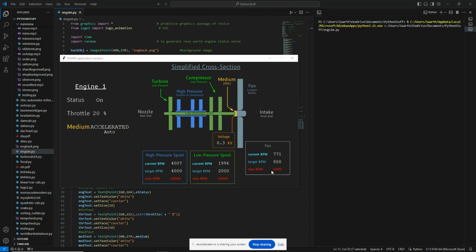So if something that's spinning at 4,000 RPM with this large of a radius is compared to something that is spinning at 10,000 RPM with a smaller radius, they would both have the same linear velocity at the tip of the fan blades. Therefore, they would both not break the speed of sound, but would break the speed of sound if they went any faster. Because of this, the fan in the front is only able to spin at a 4,000 RPM value, whereas the low pressure spool and the high pressure shaft are able to spin at a much higher RPM value before breaking the speed of sound.